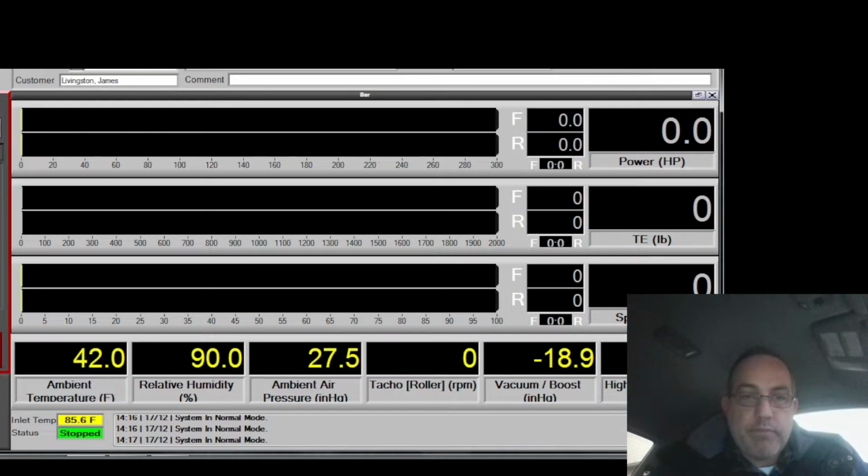yeah, it's annoying. Okay, now this one has a much higher latency at 14 volts, not much higher. It's 0.1 milliseconds, but that's going to make it run really rich right this second until these new low IPW settings get flashed, which is going to happen here in a second. I'm going to flash these again.